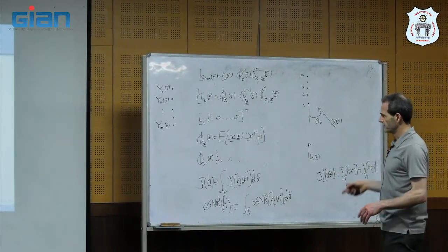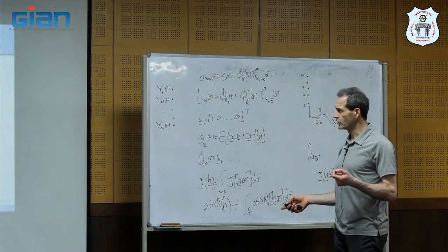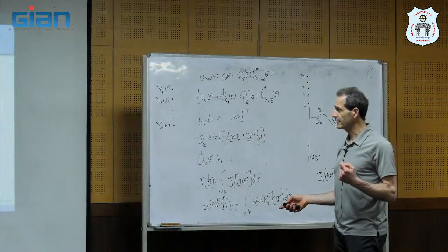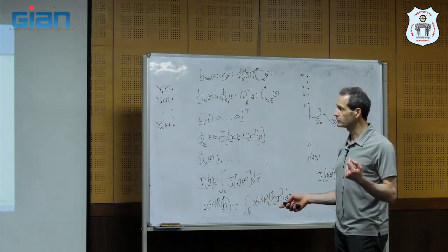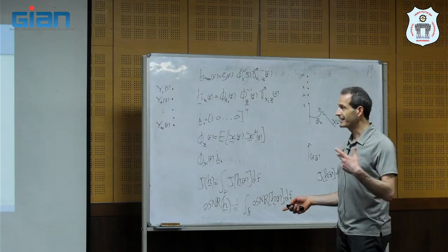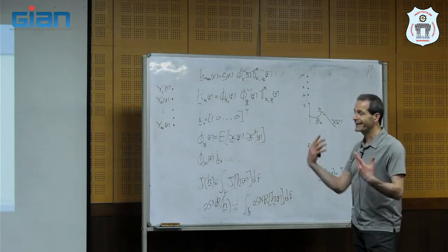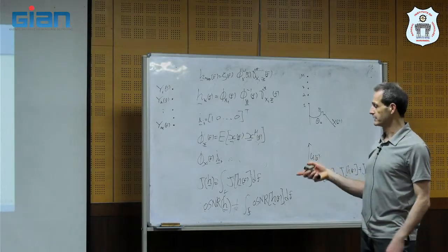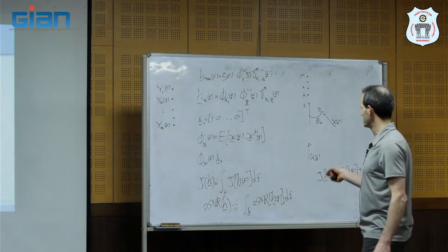So if I have a big noise reduction when I add even one more sensor, from 1 I jump to 2, I can reduce a lot of noise because now I can have spatial information. I can separate between the desired source and the undesired interference.